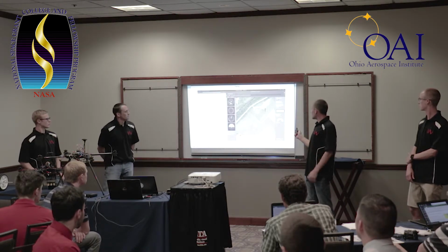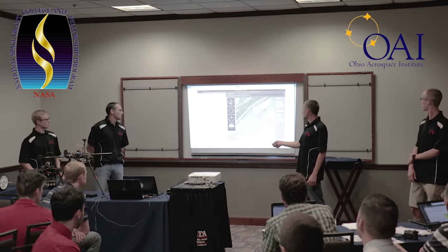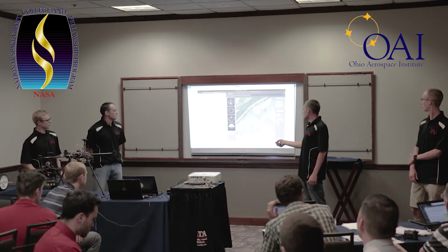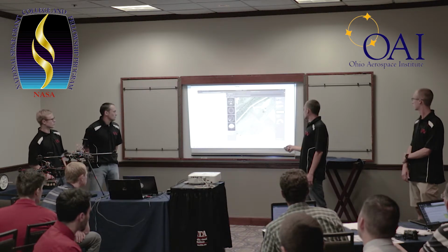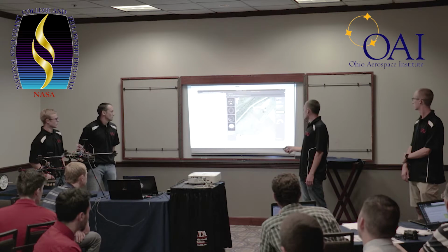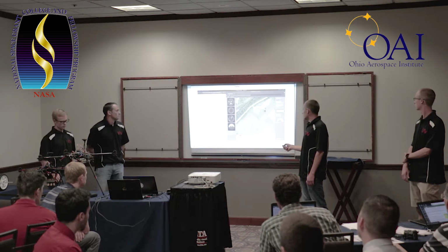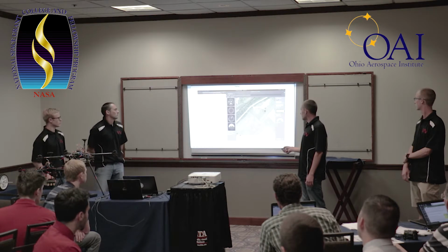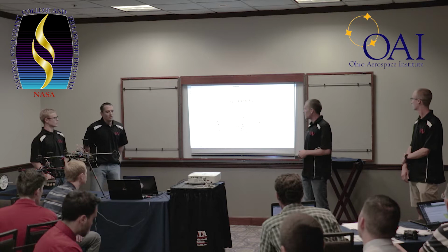Here are some screenshots of this, doing this in testing. You can see here, it launches, so it converts everything to ENU coordinates for the flight controller. It flies the course, tells you some nice things, number of laps, all that good stuff. And then I quickly interjected and sent a little battery signal for fun, and it went into landing all on its own. Any questions?